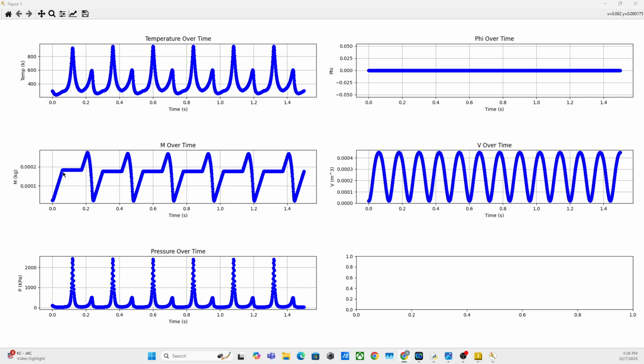But once the intake valve closes and the compression stroke starts, the gas is compressing but no gas is leaving or entering the cylinder, so the mass stays the same. And then when you open up the exhaust port, so this is intake, compression, and then expansion. Fuel injection would be right in between here. You'd normally inject fuel right here.